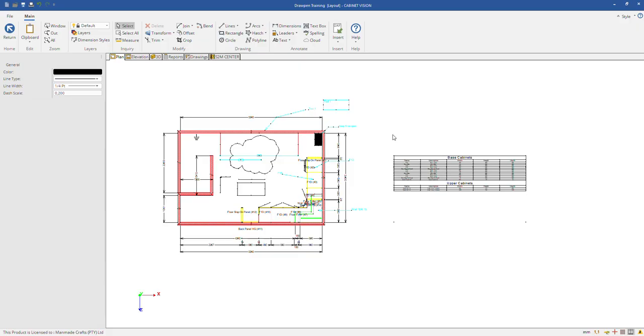Okay. Let's see if your DXF format is correct. So go into CAD, into plan. I go to CAD. I go into insert. Press on the three little dots. Go and find your DXF. I just pulled it.